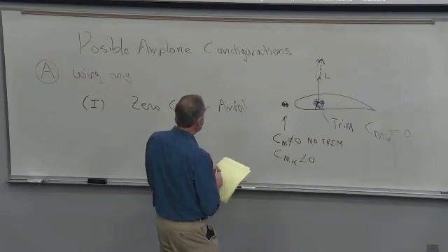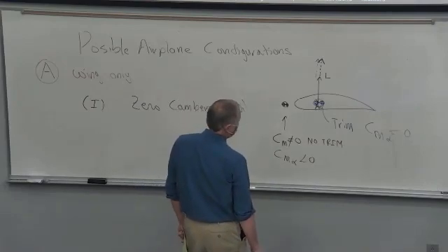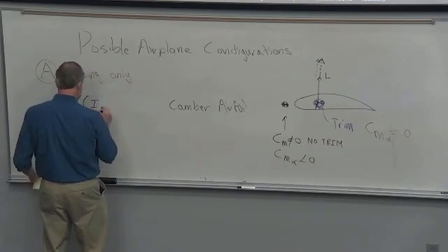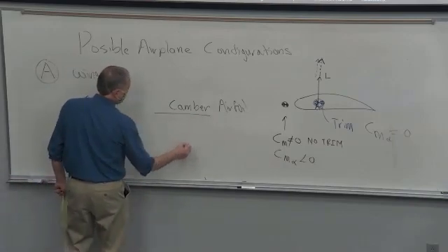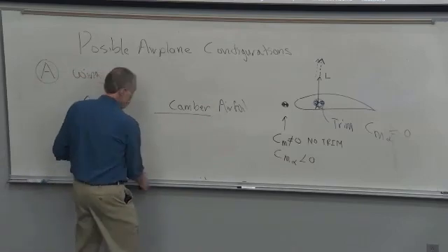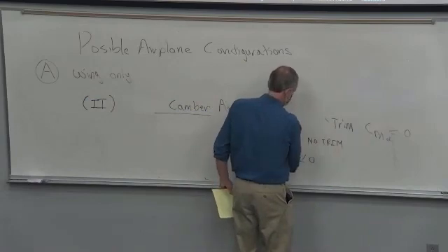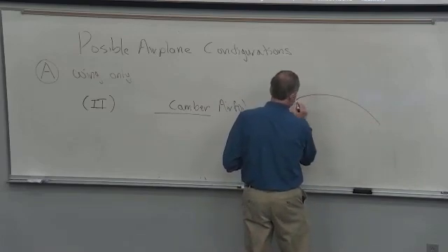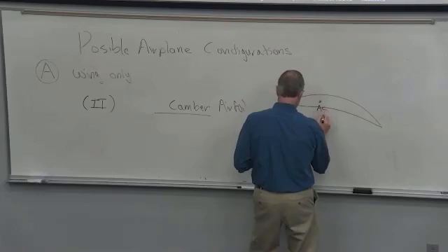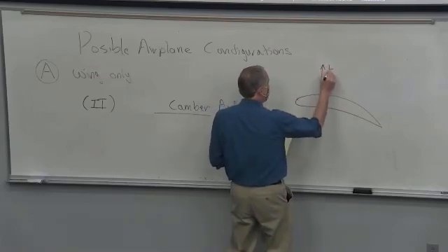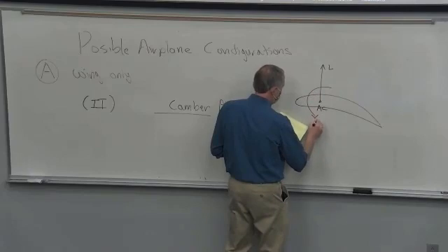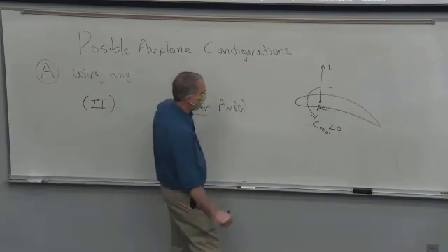So let's try a different airfoil. So that was symmetrical. Let's try a positive cambered airfoil. This is option 2, a cambered airfoil. There's the aerodynamic center. The lift is acting at that. And with a cambered airfoil, you get the pitching moment negative. So I drew it in a negative direction, down like that.